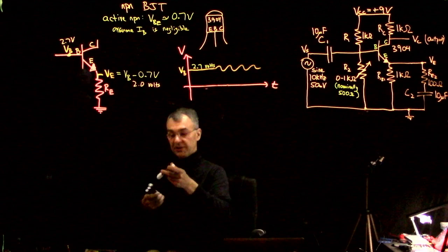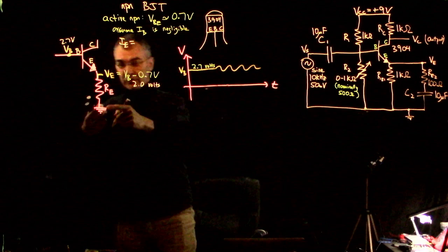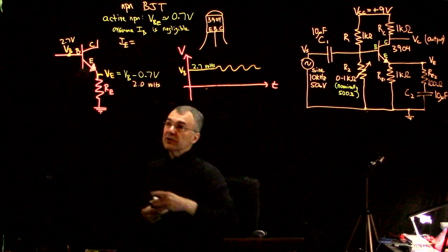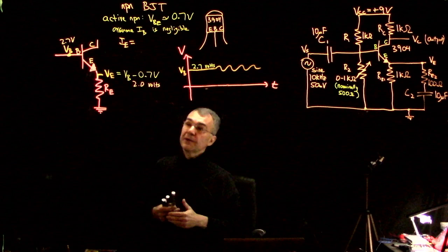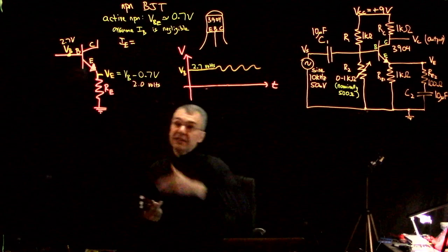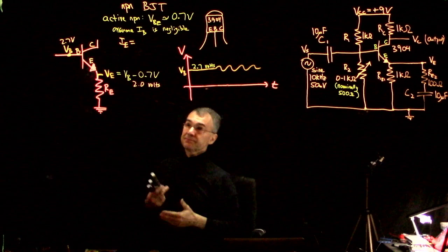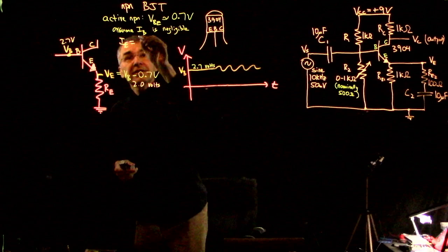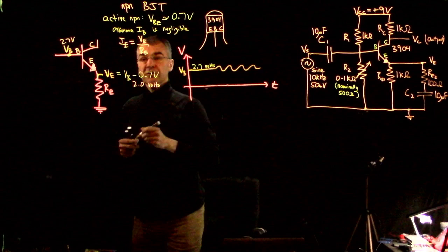So now IE, of course, depends what this voltage down here is. In all of the emitter follower and common emitter amplifier circuits we've drawn to date, this voltage down here has been ground. Sometimes you make this a negative voltage called VEE. Like if this is VCC up here, this is VEE down here. So I'll just write it assuming that this is ground, but you want to use Ohm's law in a way that correctly uses this voltage down here. So this would be the emitter voltage divided by this emitter resistance.